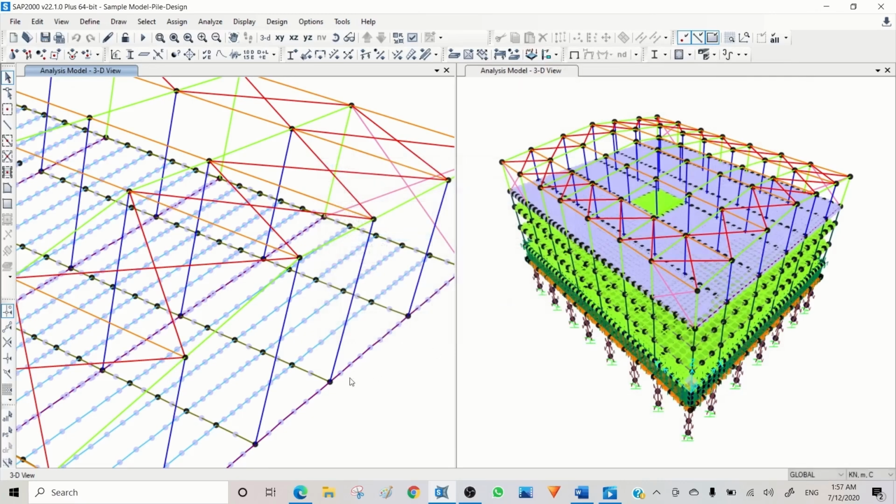Why am I doing this? Because I want to add the concrete flange as a part of the composite section, but I already have the slab here. So if I do this, I literally add to the weight of the structure and the load of the beam. That's why I'm using zero-weight concrete, to use the stiffness of the concrete as a flange, but not use the weight of the concrete on top of the flange in addition to the slab modeled here.